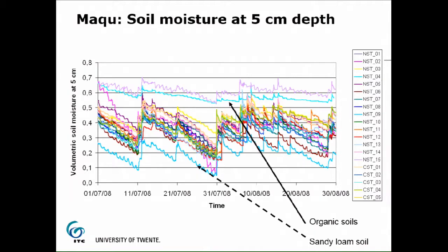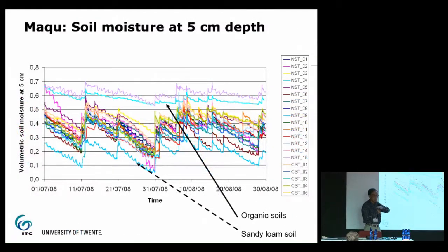What you see here is that when it has a jump, you notice that there's a precipitation event. And then if you look at all the 20 curves here, meaning the kind of phenomena here is larger scale, covering the whole area because they are very, very much separated. But then if you look at the individual curves, it tells you actually about the soil texture information here. So it gives you a lot of information about the soil texture and what is influencing the soil moisture pattern.